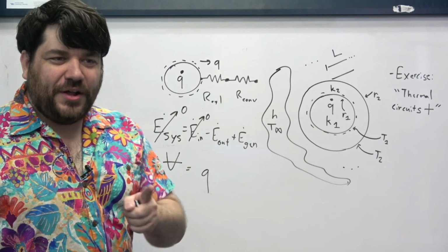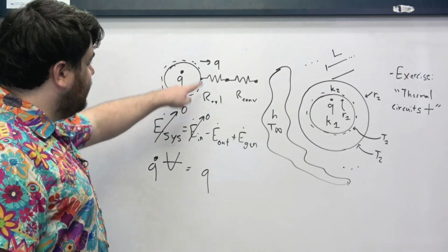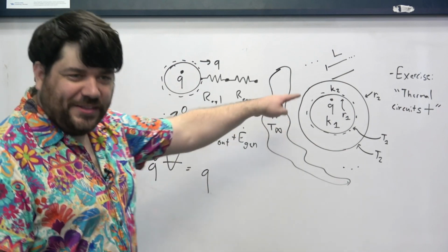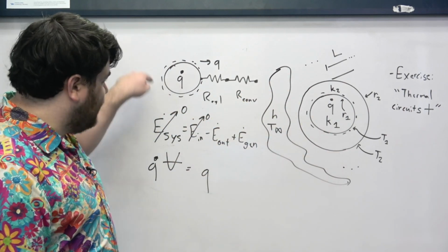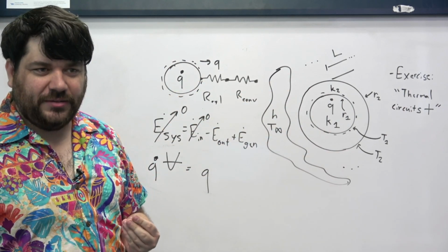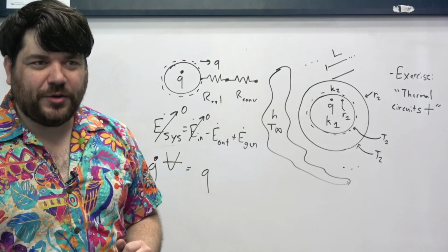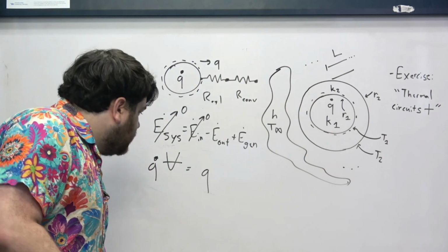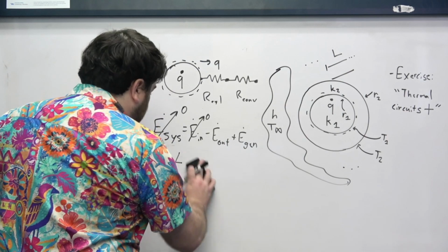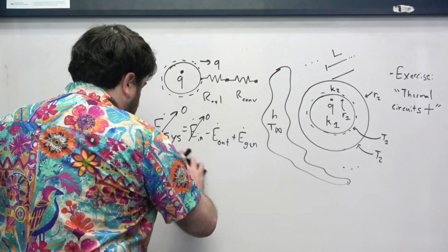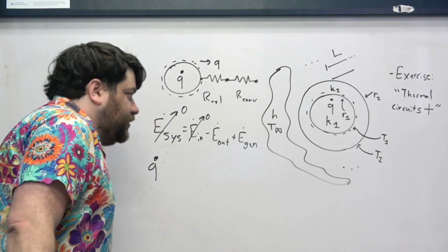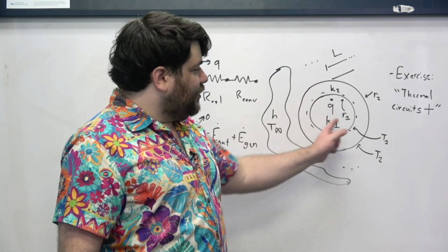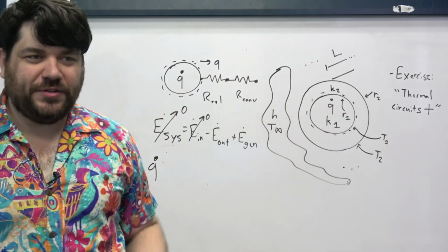Important to remember, the volume that we're considering is specifically the volume of the cylinder core. It's not the volume of the whole thing. It's just of the little core where the heat transfer is occurring, or pardon me, the heat generation is occurring. So what is the volume of a cylinder? Well, we just take the cross-sectional area of the circle and project it forwards.